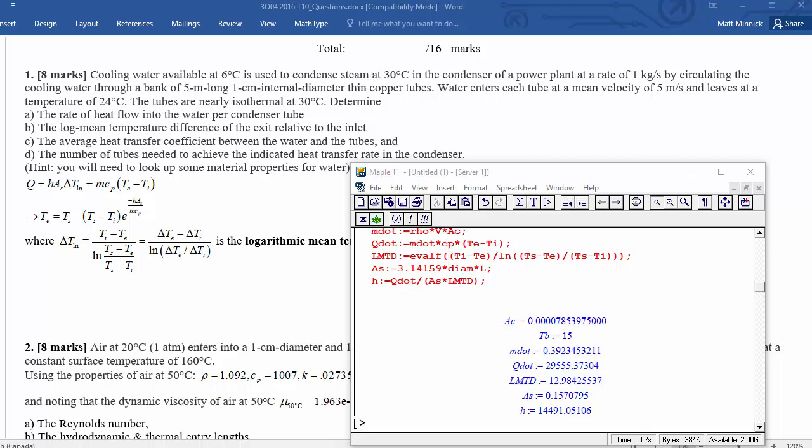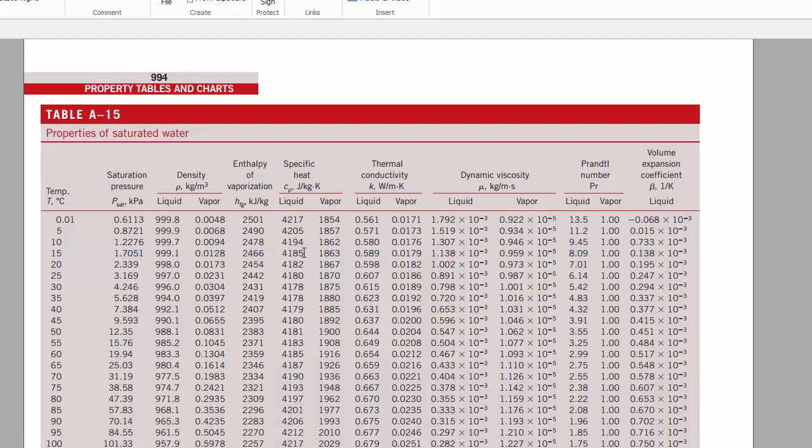So specifically, we're going to need to figure out how much energy we get by condensing water vapor into liquid water at 30 degrees. That also is in this convenient appendix here in the textbook. What a textbook. We've got an enthalpy of vaporization here of 2431 kilojoules per kilogram.